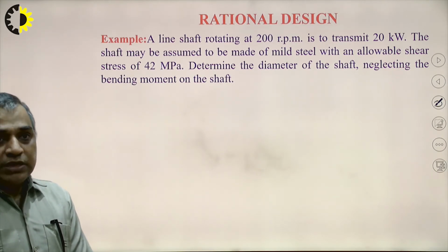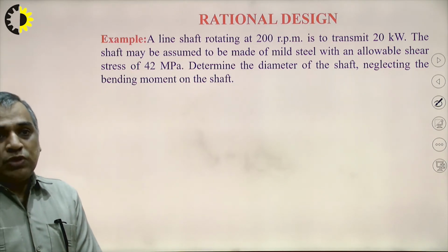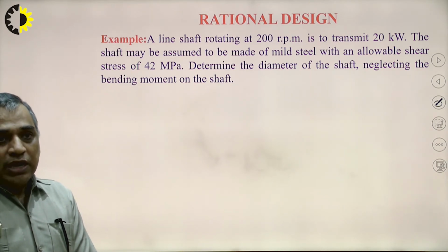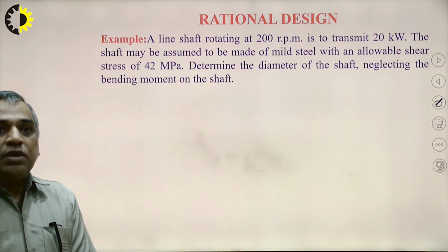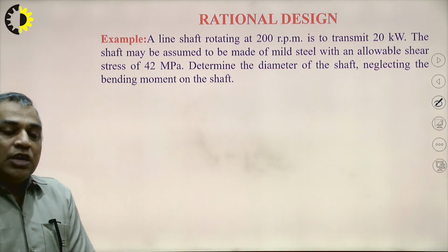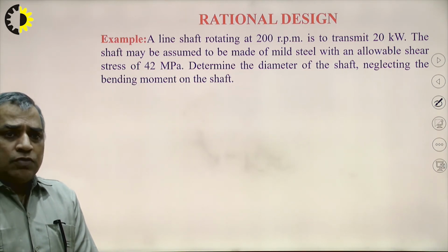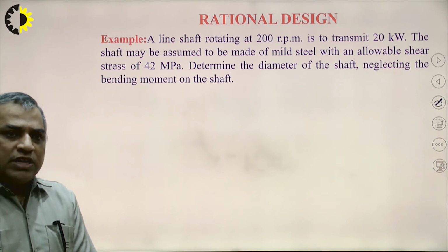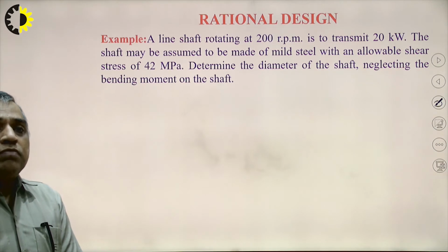We can apply the maximum shear stress theory, or we can determine the induced stress in the application, and we have the allowable shear stress. On that basis, we can formulate an equation and solve that equation. We will get the diameter of the shaft.